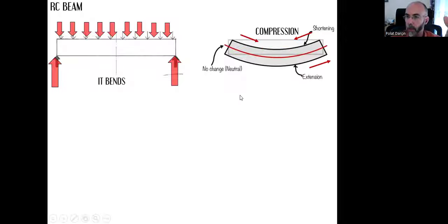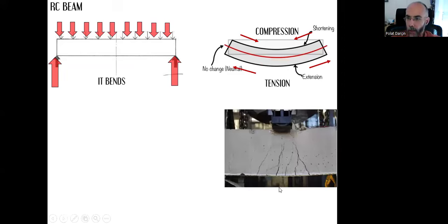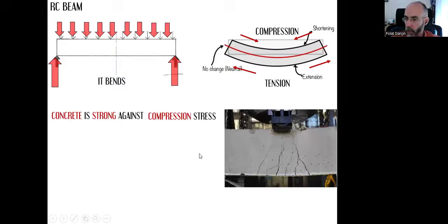However, the lower part is different. This time, molecules are forced to go apart from each other, and they are pulled away. That's where tension stress occurs, like that. And we know that concrete is a very strong material against compression stress. So wherever there is compression, we need concrete. It will hold better against compression stress.